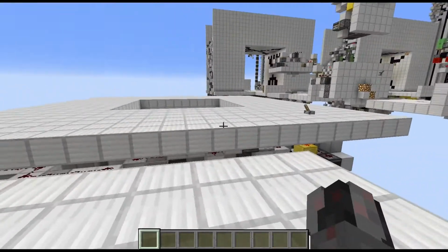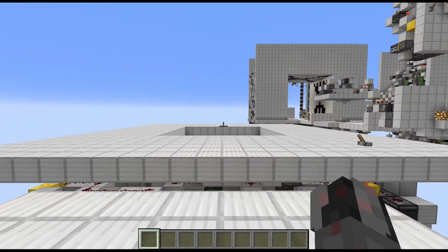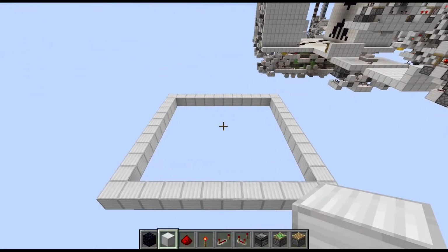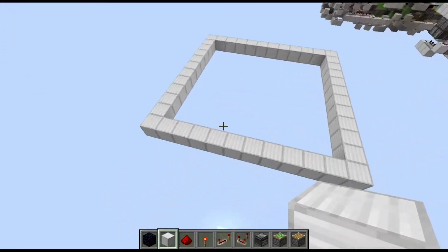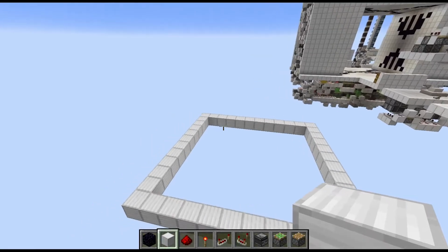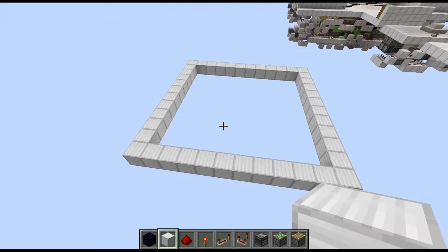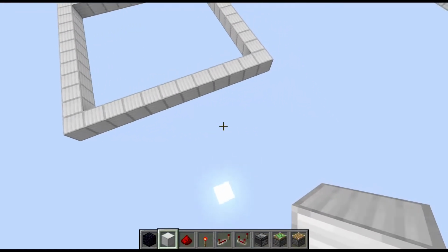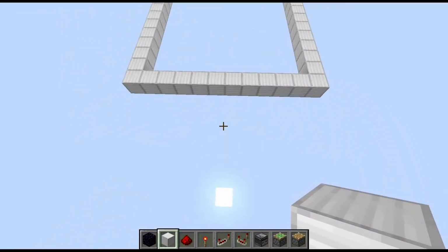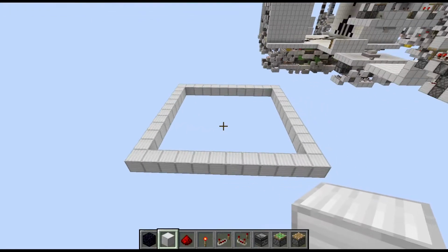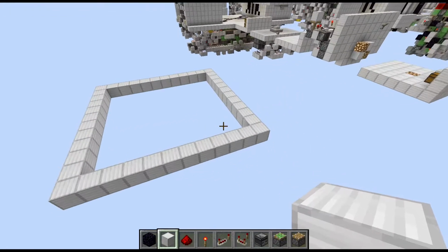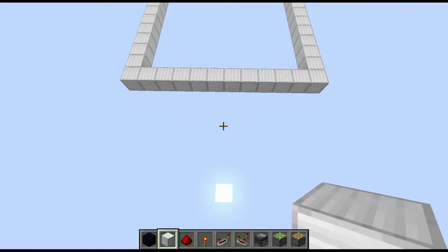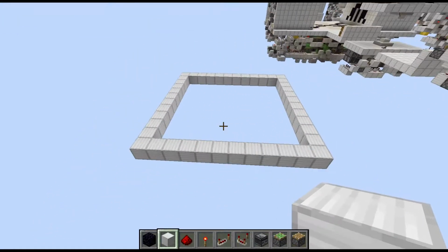And with that out of the way, let's show you how to build this trapdoor here. The first step is actually marking where the opening will be in the future floor. So in this instance here, I have this 12 by 12 ring with the obvious opening here being 10 by 10. Due to symmetry, I will from now on just show you how to build the front quarter here. The other 3 quarters are built exactly the same. The only difference is, well, they are rotated around. So I will show you how to build this quarter and then copy it another 3 times during the cuts.